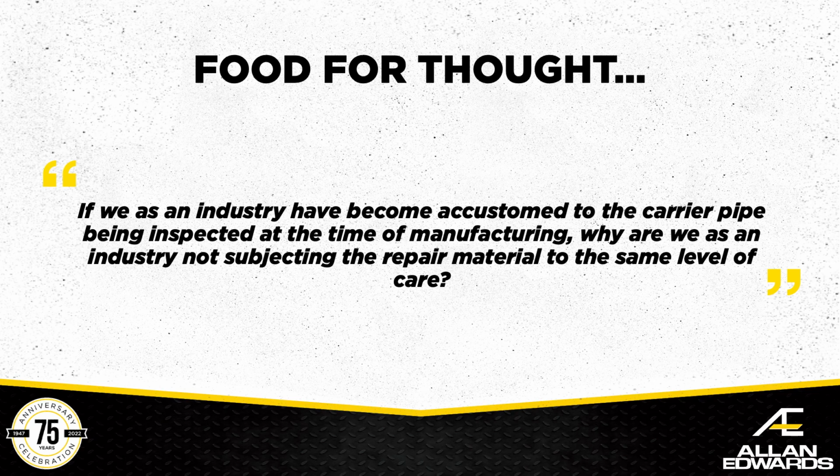You know, like I kind of said, if you're going out, you're buying pipe, you're subjecting it to the most complete NDE that's out there, some sort of UT, maybe some X-ray, this or that. If we become accustomed to inspecting the carrier pipe to that rigor, why aren't we doing the same rigor or the standard of care to the sleeve material? Right?